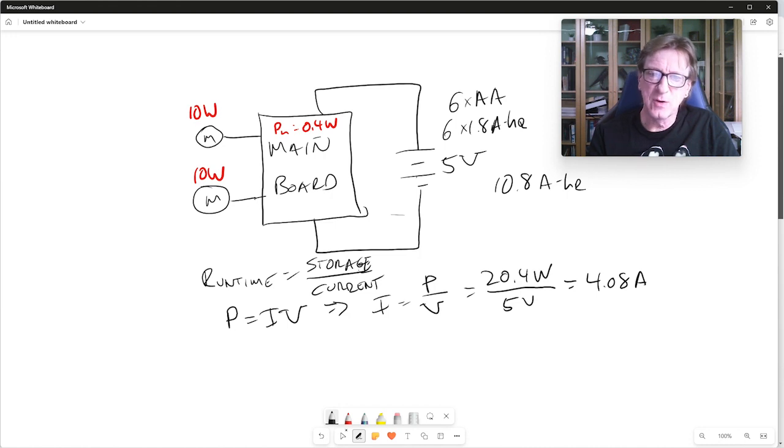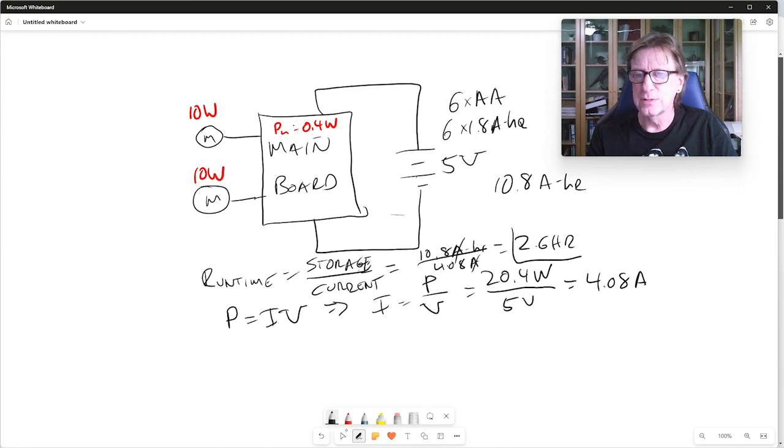So that's my current. So now I'm going to put this into my runtime equation here, and I've got 10.8 amp hours divided by 4.08 amps. And you see the amps cancel and leave me with the hours. And when I did that, I got 2.6 hours. So that's the runtime. So you see that while we got well over 100 hours with just the main board, when I put those motors on, the time that the battery will run drops dramatically. Now I'm down to just two and a half hours roughly.